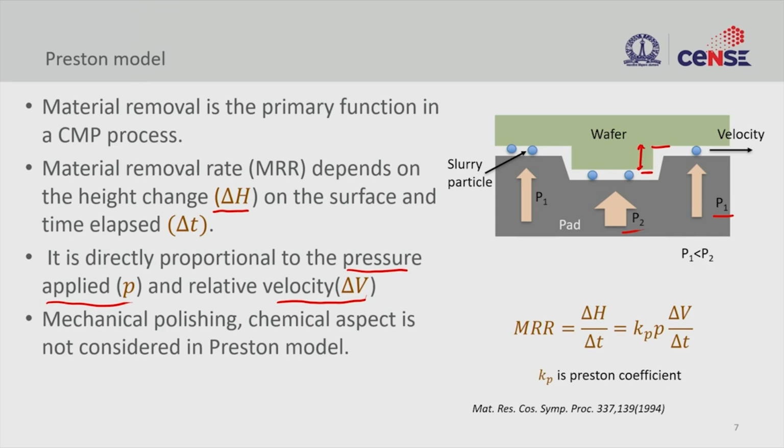Just by applying a pressure, right, putting them under a certain pressure is not going to help you in a stationary function, right. Either wafer or pad should move, or both of them could move. So, you want them to move at a certain velocity. The faster they move, the removal rate is higher, right. So, the pressure and the velocity also play a huge role in dictating the material removal rate.